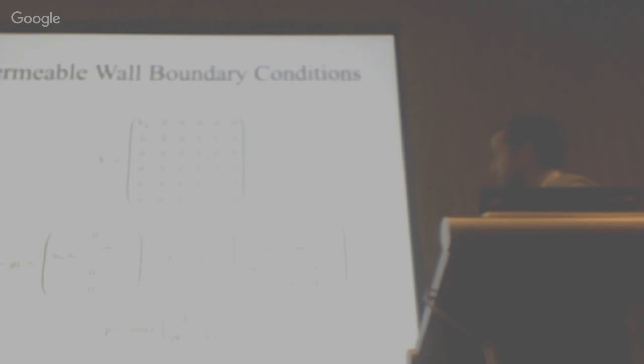And your viscous penalty data is particularly worth noting. This is basically, here again, a non-slip boundary condition. Slightly different again because of the injected velocity. And then these last terms here are basically a mass and energy balance at this wall. They basically ensure that the amount of energy and mass that's being injected is equal to the sum of the inviscid and viscous flux at that wall. So that's how those penalty conditions work.